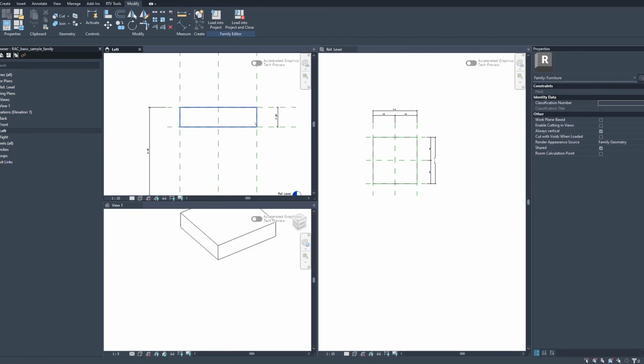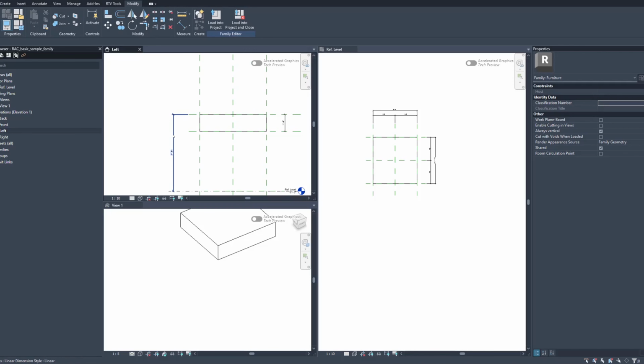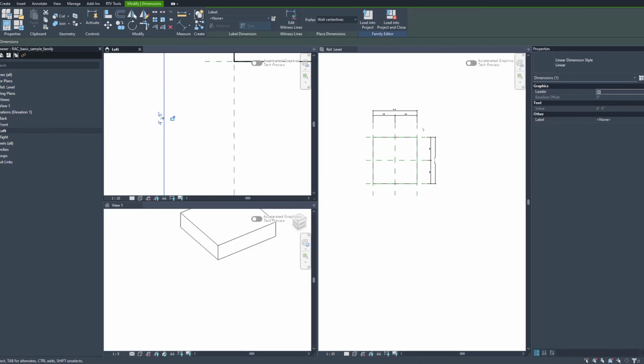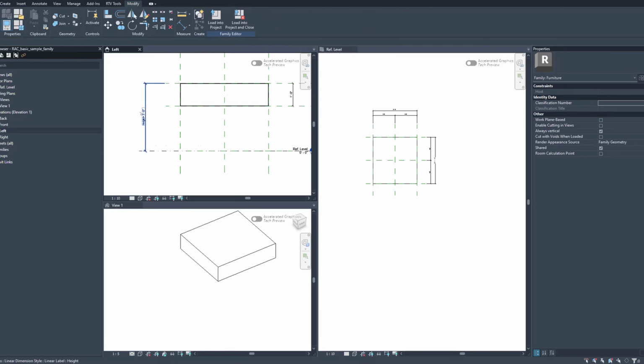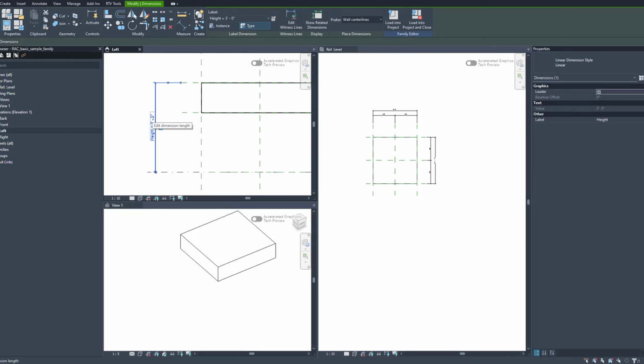Now that that's locked with this geometry, I want you to click on this dimension, and instead of it saying linear dimension, I want you to say this label. Look at that! And I want this label to say height. And guys, look what we just did. Now we created a parameter, a dimension, a lock command. Here's all that information. So now when I click on this again, because of what we clicked before, we can go ahead and click those particular things. That is really, really cool.